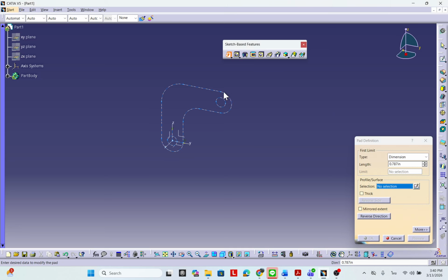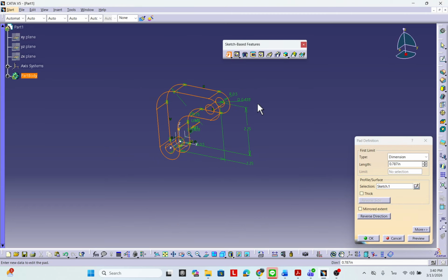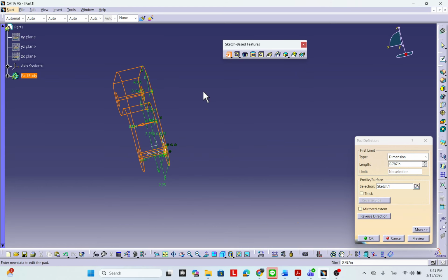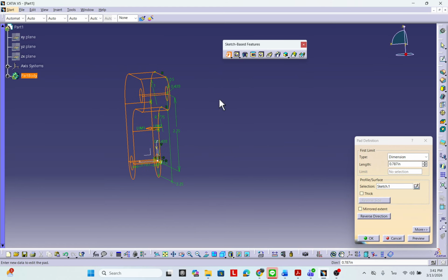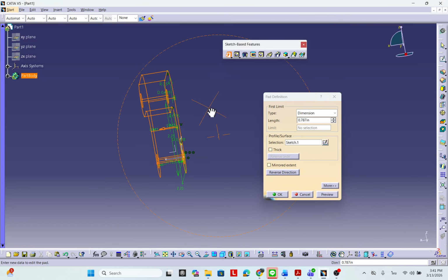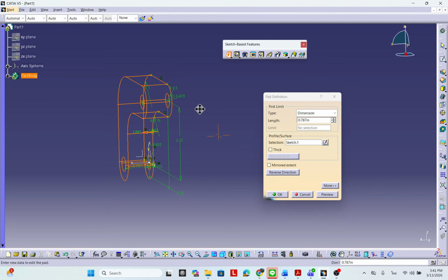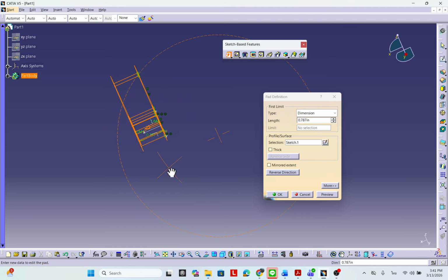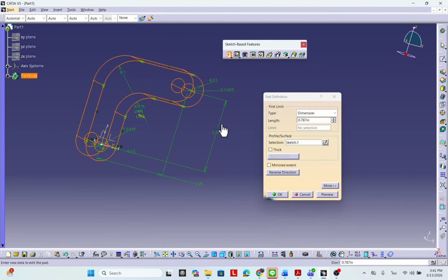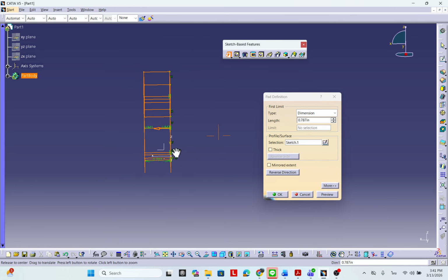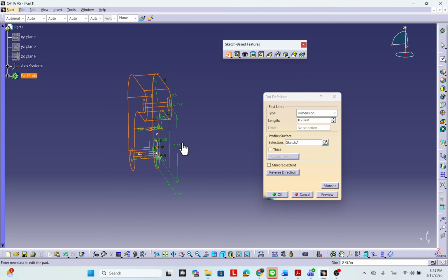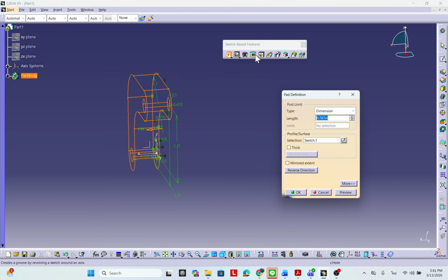And the first command is the solid. I will tell you and show you how to create the first solid. This one is the pad. Pad just creates the thickness of the profile from the plane, by default, from the sketch plane, because on this plane you already made the sketch profile. You click on this command, click on the profile, stay inside of the profile, and use the surface selection.